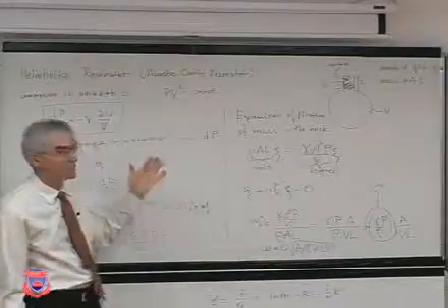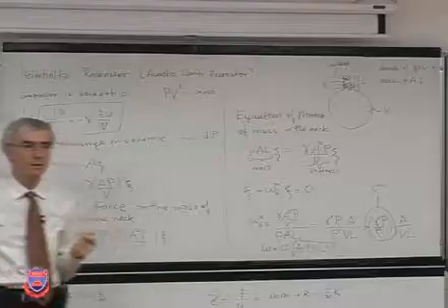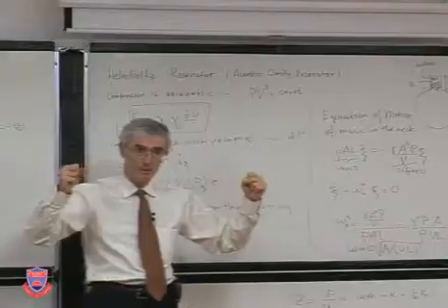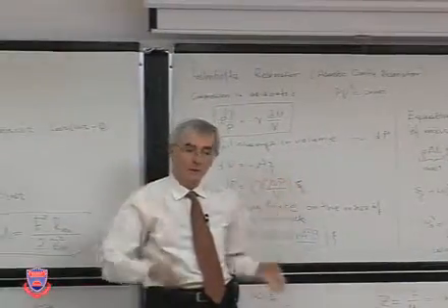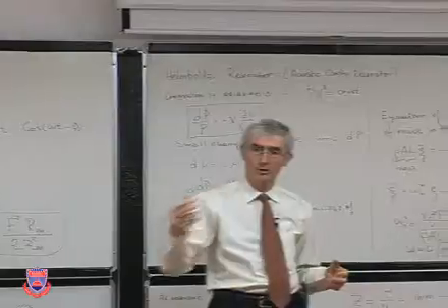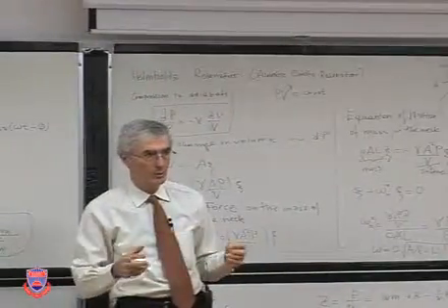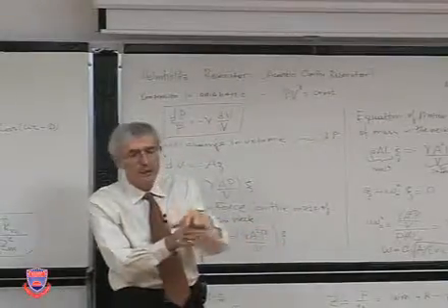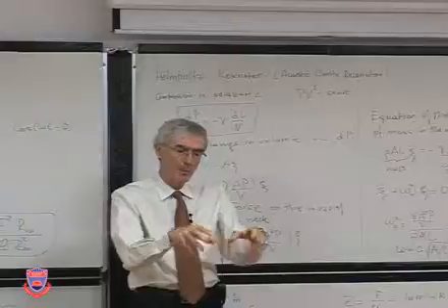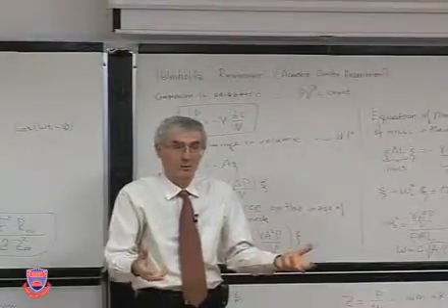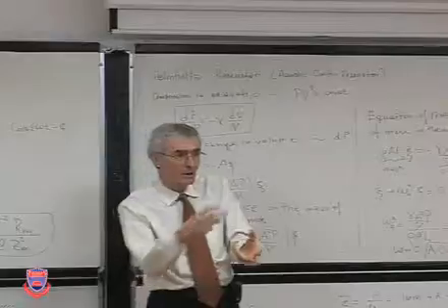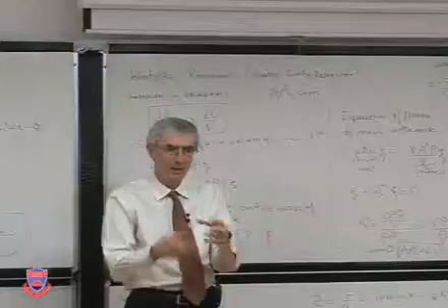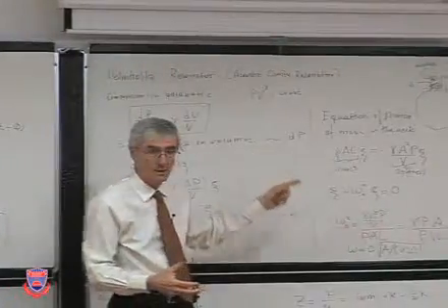Now, what do you use these for? Helmholtz resonators are used in a number of different applications. They could be used as sound absorbers in theaters, in automobiles, what's called induction noise in an automobile. They actually put a long volume; the shape is determined by how much space is available in the engine, because you don't have much space in the engine. So it can just actually be a very funny shape. It doesn't matter as much, okay? And it acts like a Helmholtz resonator.